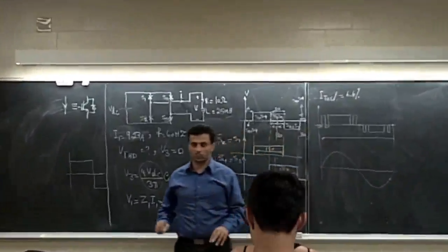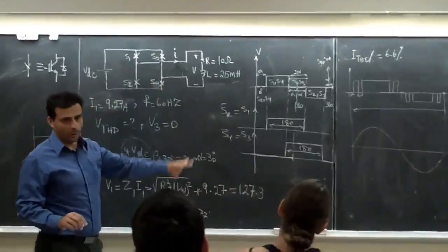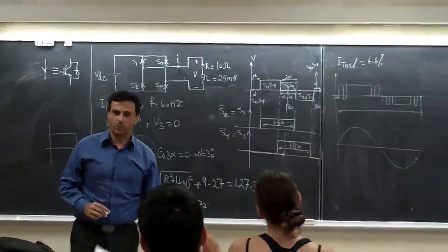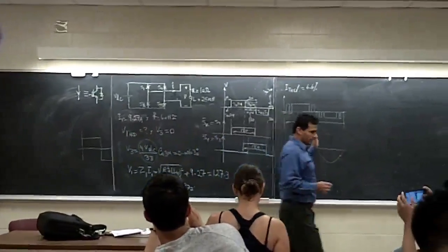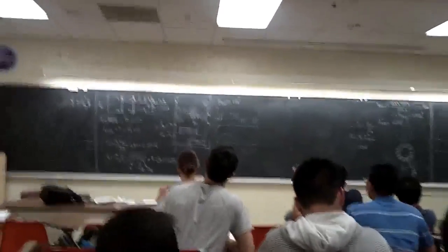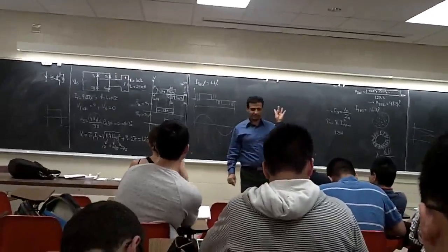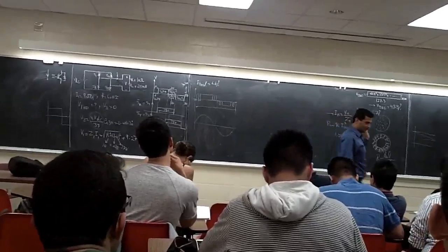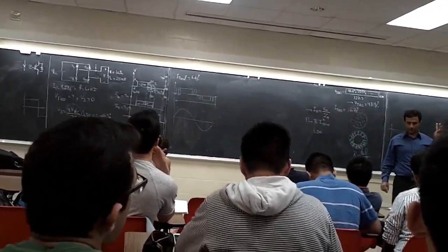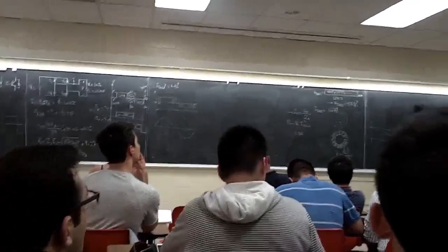Now think about doing this one; it will be more complicated. So this is the harmonic elimination we talked about. Now we want to talk a little bit more about traditional harmonic elimination. You calculate those alpha, beta. For example, if I want to eliminate 3 harmonics, the 3rd, 5th, and 7th, how many parameters do I need to control? 3, right? Alpha 1, alpha 2, alpha 3. I don't give that one in the exam to you. Why? It's not too hard.